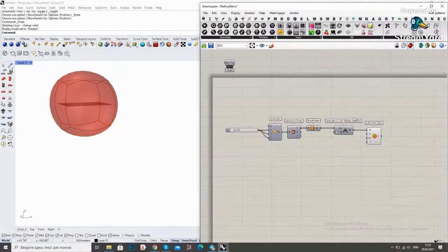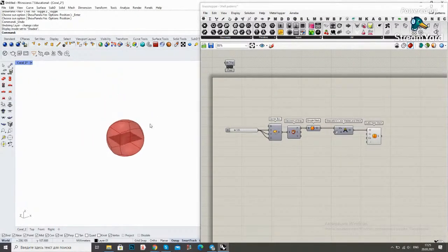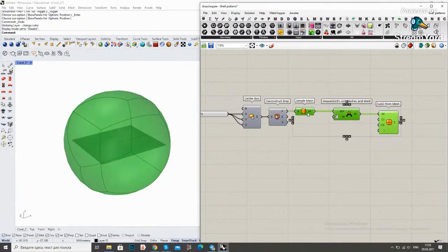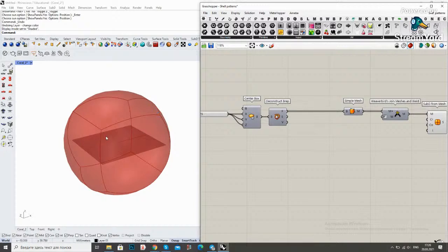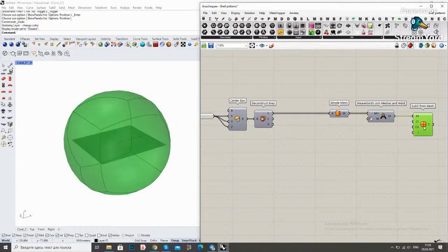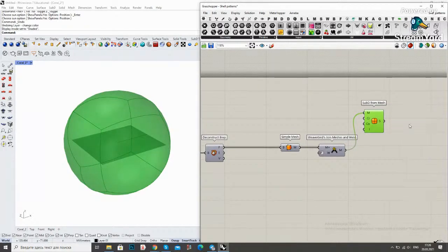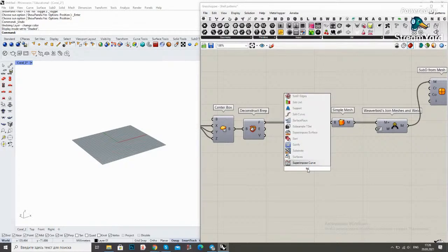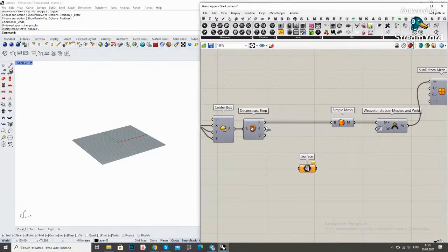All right, so you can see that if we apply subdivision directly to a cube, it basically gives us just a sphere. That's kind of nice, but normally we want to achieve something more designed. We want to have more control of the design, and now we don't have any. So that's why we need to start introducing some more edges, actually edge loops, to this basic geometry. I'm going to keep this somewhere here and preview it for the moment. And let's see how we can start adding more control and more detailing to this geometry.